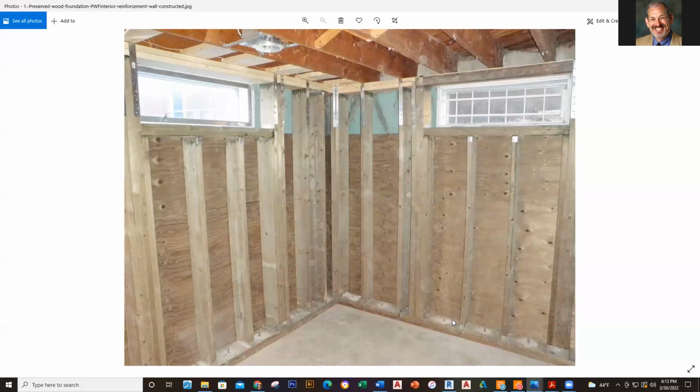permanent wood foundation. It's treated lumber, so it's waterproof. They call that pressure treated. Basically, you put that in place under the surface. There are a few different names for it, but essentially it's treated so that the wood will not rot and the wood will not leak. And we basically put that in. So that is all that is between your basement and the dirt outside. They put one thin layer of visqueen, but that's just a vapor barrier. The wood keeps everything out. So you have that right there, and that's what's in the basement. That's the first thing that we did.